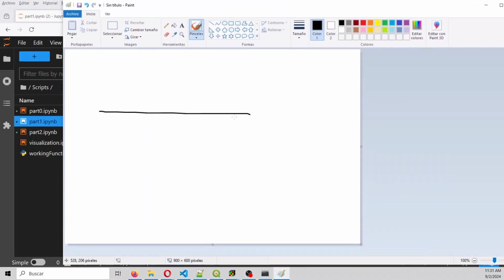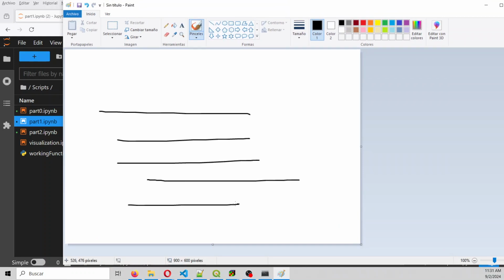Layer 1, layer 2, layer 3, layer 4. In GemPy, you give points that define the bottom of every layer. That is an input, but you don't give only the points, you also give the orientation, that is the perpendicular.